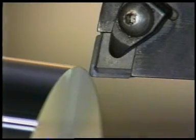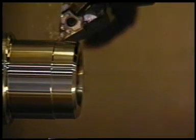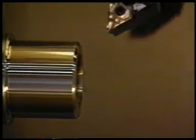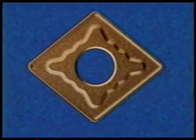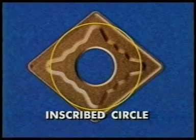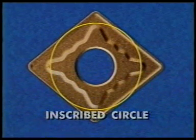However, a larger radius also generates greater radial cutting forces and runs the risk of vibration. The quality of the finished turn surface is mainly from a combination of the cutting tool's tool nose radius and the feed per revolution. Insert size is designated by the largest circle which can be inscribed within the perimeter of the insert, called the inscribed circle or IC.